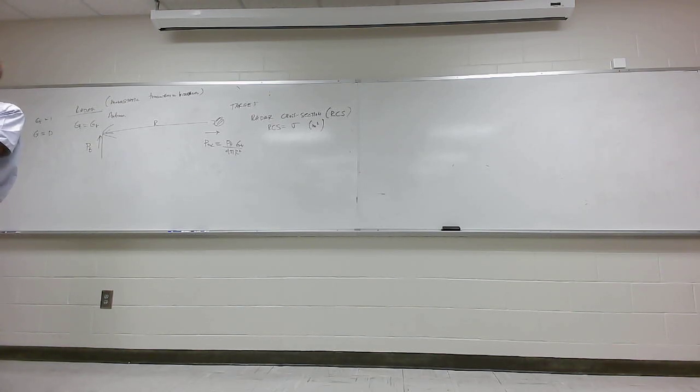It would be an order of magnitude, maybe 2 orders of magnitude less than this, when the wavelength is many diameters. Now as the frequency gets higher and the wavelength becomes about the same as the diameter, the radar cross-section approaches that of the real cross-section.